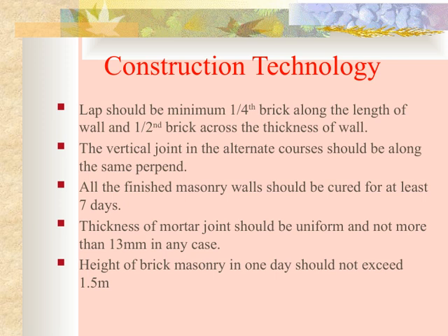This staggered pattern enhances the wall's strength and prevents continuous vertical joints, which can weaken the structure. All finished masonry walls need to be cured properly for at least 7 days. Proper curing is essential for the masonry to gain the desired strength and durability, preventing cracks and ensuring longevity.